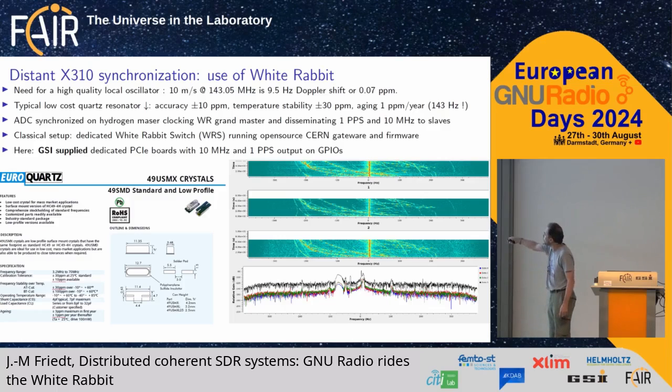And this is a beautiful straight line because we're locked on the hydrogen maser. If you were to run this on a standard TCXO, a temperature-controlled crystal oscillator, you would see this line drifting in all directions because of intrinsic local oscillator motion. And so this beautiful straight line, which allows fine Doppler shift measurement, is thanks to the high stability local clock.